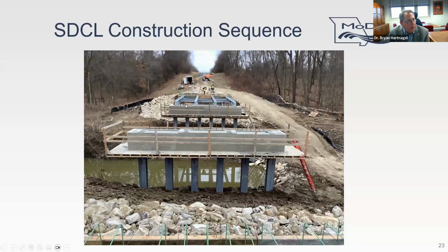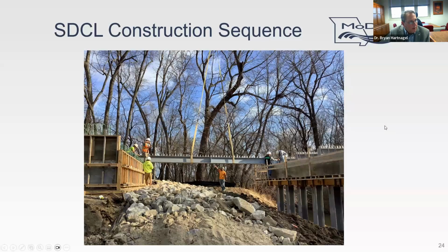Started to set the girders in the far span there. You see 4 girders. All of these bridges had a 24-foot roadway, 7-foot girder spacing with 4 girders, and some diaphragms that were bent plate or channel diaphragms. So pretty simple to put together. You just set them on the vents, as I said, in simple spans. Here you see them picking and setting girders. Obviously, this wasn't a trackhoe. This was a bigger crane, but this was a rubber-tired crane instead of a big track-mounted crane that may be necessary to place girders of that other material.